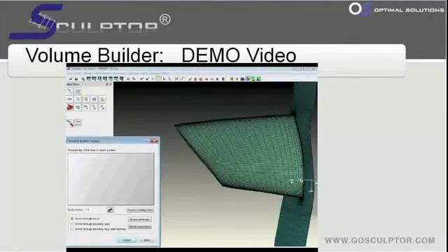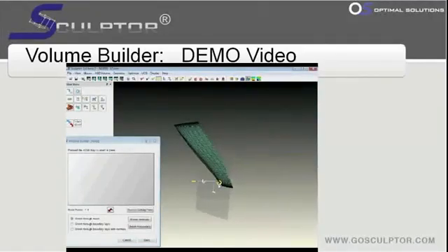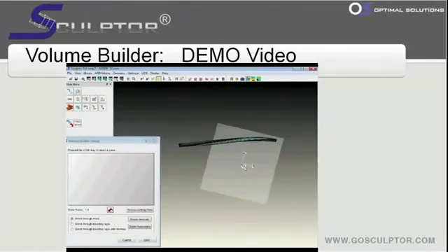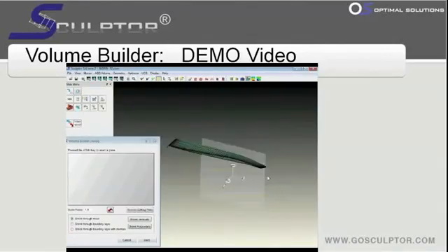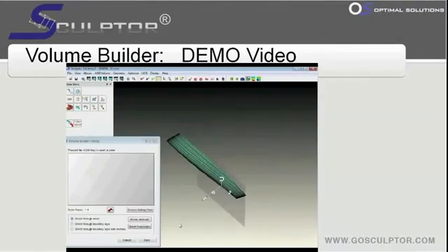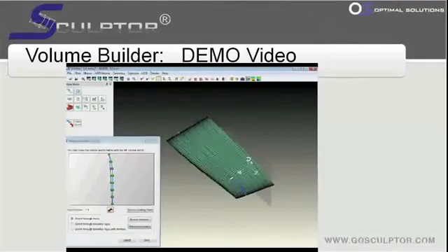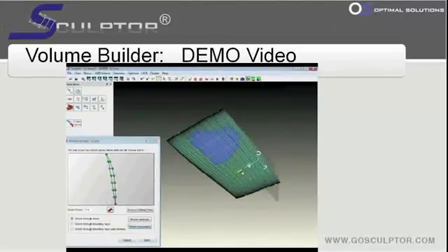And then these control points are simply moved to perform a deformation. In this case, we are creating cutting planes where we place a set of control points and then automatically shrink those to fit right on the surface, both the top surface and the bottom surface of this blade. And with a few mouse clicks, you can move the control cutting plane and create another slice and another slice until we have enough control points.